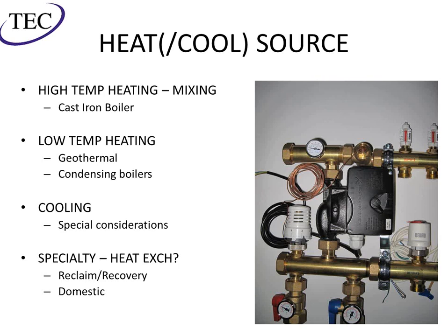If you're doing cooling, there are special considerations you need to take. Most manufacturers will recommend that you be in at least 5/8 inch tubing or higher. They do have tighter delta T's, tighter tolerances, and most notably, on the control side, you need to be cognizant of the dew points and whatnot to make sure there's no sweating going on.